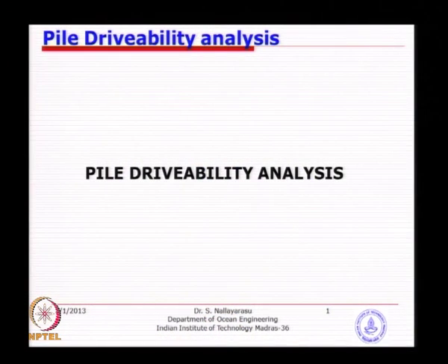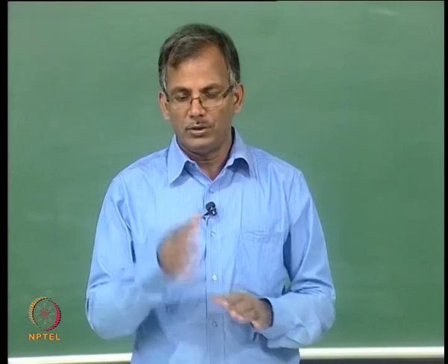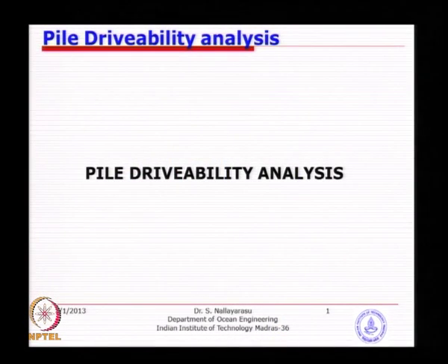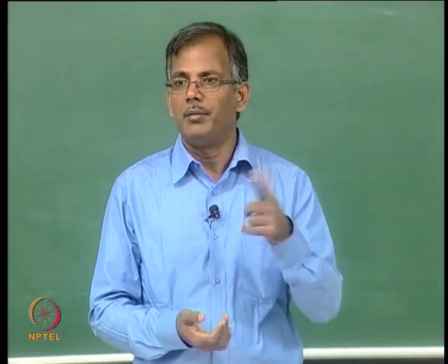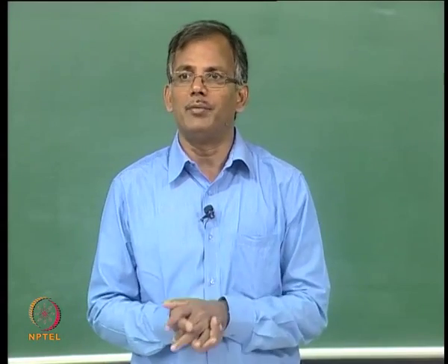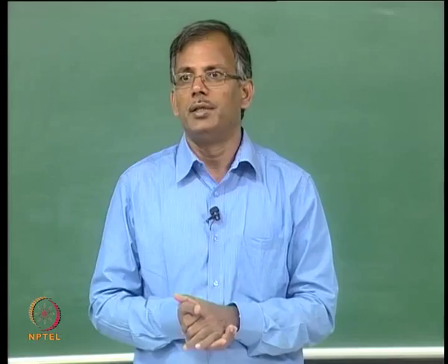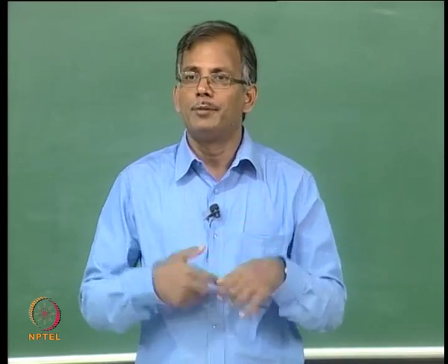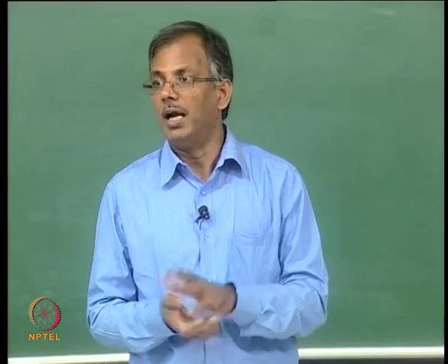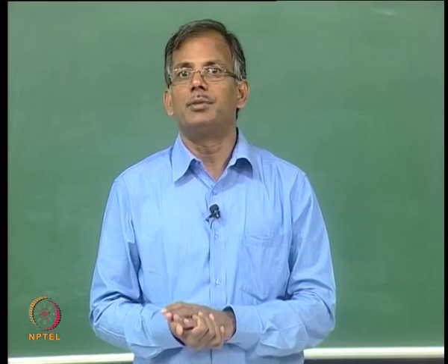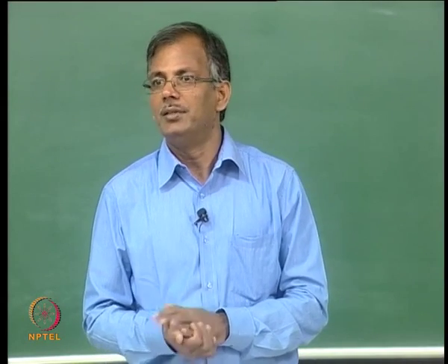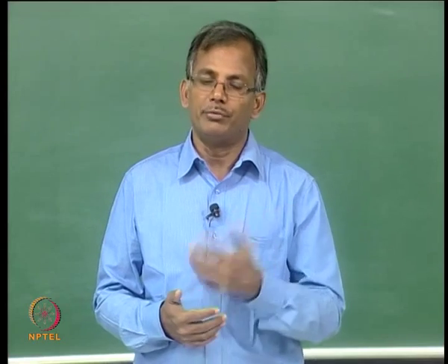So, this contains several parts. Of course, you need to have a good understanding of the soil, the pile and the overall system behavior. We are going to look at them one by one over the next maybe 5-6 classes: a basic understanding of the system, hammer, pile, as well as the soil behavior at the time of driving, and somehow we have to simulate it numerically in a computer program, so that you can predict the effort required to drive. Ultimately, what we require is the effort in terms of impact energy. Then you can select a suitable hammer and take it offshore.